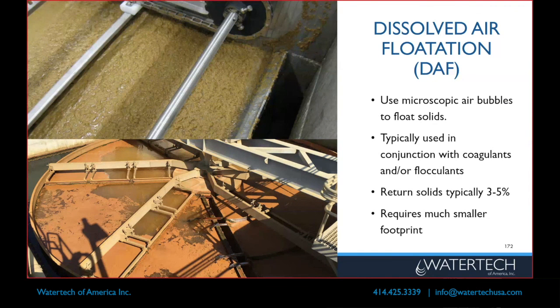Dissolved air flotation, Chris talked about that, so we won't go into it too much. Biggest benefit is smaller footprint. This one's funny actually, it's a round DAF in a square tank, kind of unique. This is a rectangular DAF. But again, using air bubbles to float those, typically in conjunction with coagulants or flocculants.